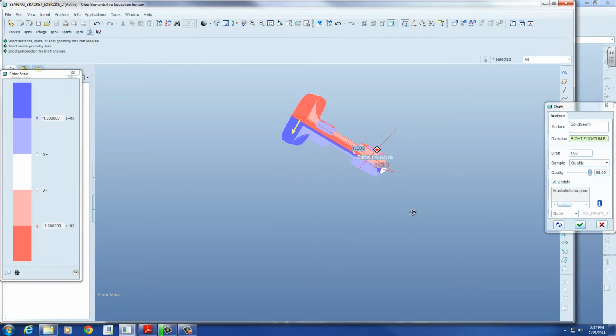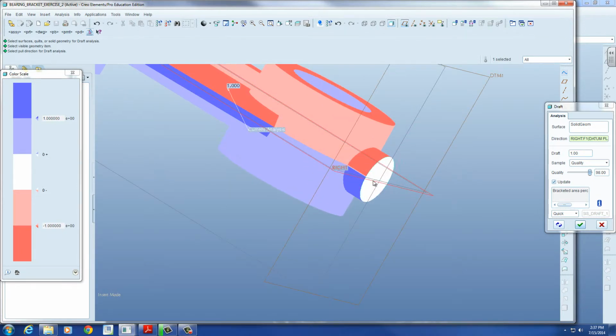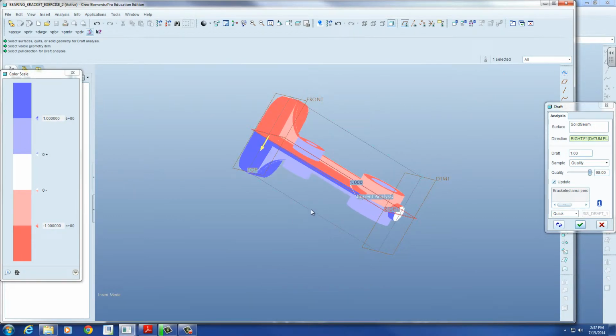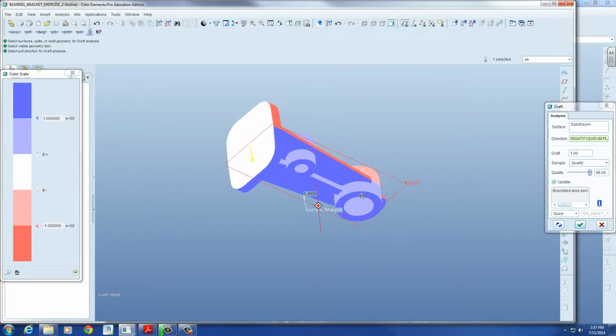Anything that's perpendicular to this without a shut off right here would have to be pulled. But since we have a hole that's going to be pulled this way, there's going to be steel up against this, and it can pull that pin out. That way we still have a flat surface for whatever's going to mate to that. Does that make sense to you guys? When I get finished with this, I'll make a tool, okay? And then we can look at it.